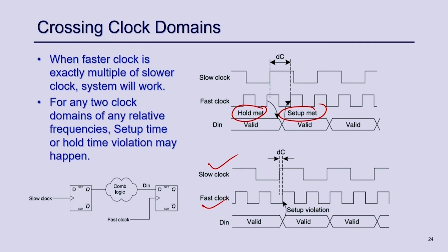So, there is a change, this is the delay in that particular clock, which I talked about earlier also, and here the faster clock comes, and this data is the output coming from this. So, this is related to this clock, right. Whenever this edge comes, this data gets updated. Here it is changing, right. At this point whenever the data is changing, the clock is also changing, and that is called setup violation, right, because at this point data should not change. This data is coming from the clock 1 domain which is the slower clock, and this data depends on this clock, and it might change based on the positive edge of this clock, and at that moment maybe this clock is also changing.